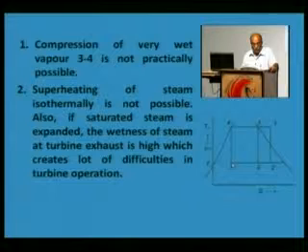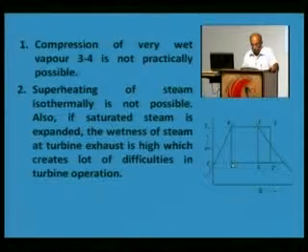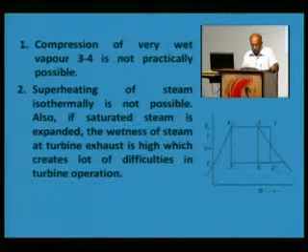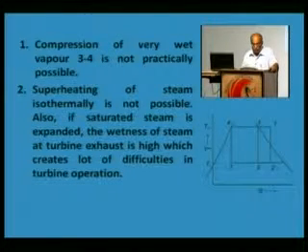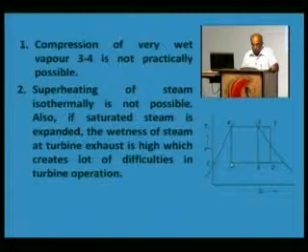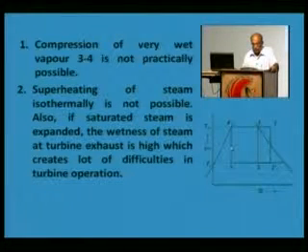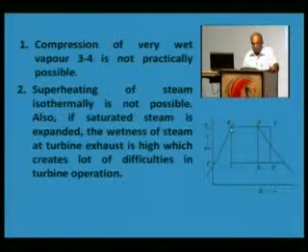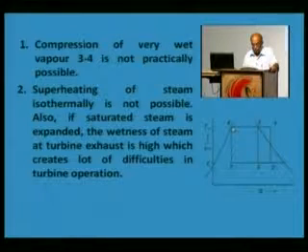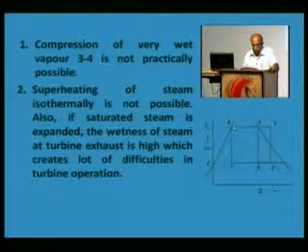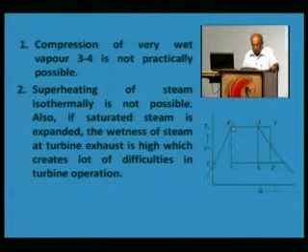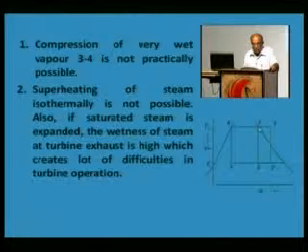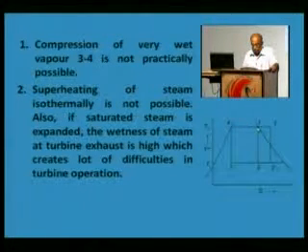At point 3, the steam is extremely wet and it consists of a small fraction in the vapor state and a major fraction in the liquid state, and to compress the liquid is not practical. Liquid being incompressible fluid cannot be compressed isothermally, and therefore this process 3-4, the isentropic compression process, is not a practical process. Then 4 to 1, the heating process is isothermal as well as constant pressure, but 1 to 1 dash,